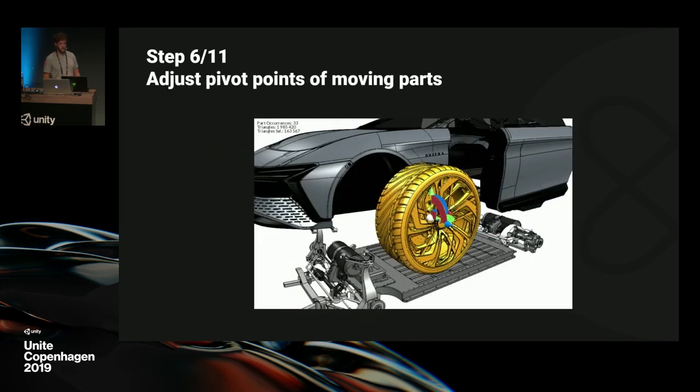Then regarding the pivot points for later animations, well, in CAD data, pivot points are not always defined in a way that can be suitable for real-time animations. So we use functions to recursively set the pivot points of each node of the hierarchy to its bounding box center, or following a 3D frame reference.